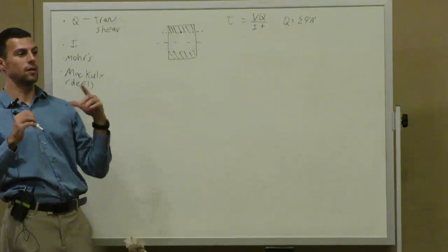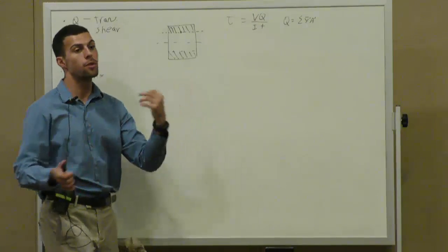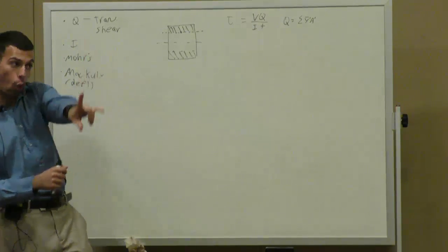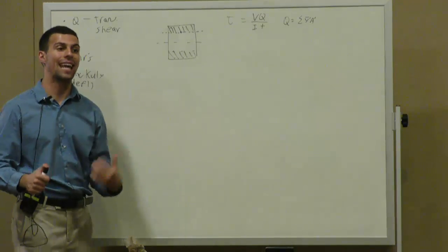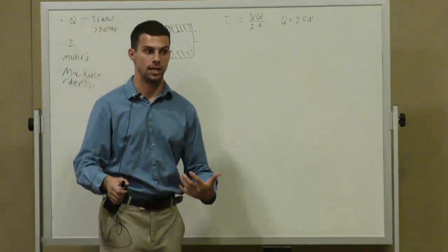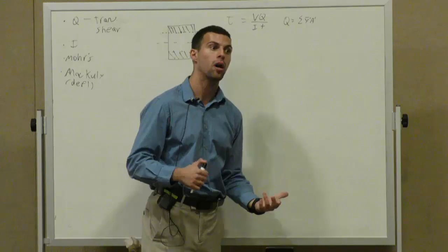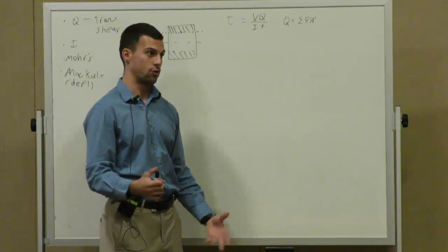Correct. It is the combination of you two is correct. It is the distance from the neutral axis to the centroid of that area of interest. The prime there means the interest. So it is the area of interest, and it is the centroid, the Y bar, of your area of interest, prime.